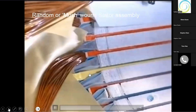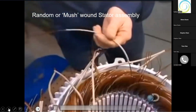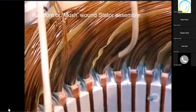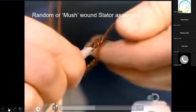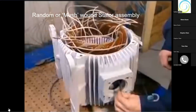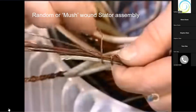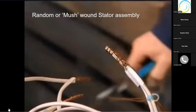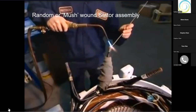Once all the coils are inserted and insulated, workers begin preparing the connection. They slip an acrylic insulation sleeve over both ends of each coil. 13 coils, 26 ends. Then they group these insulated wires into large power cables. The number of wires per cable varies according to the speed and voltage of the motor. They solder the grouped wires together, then insulate the cables.